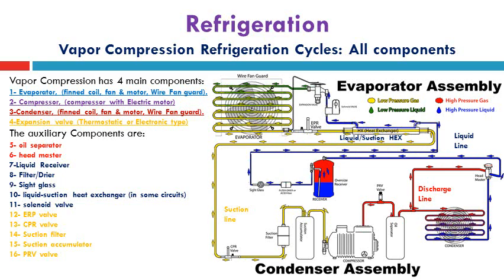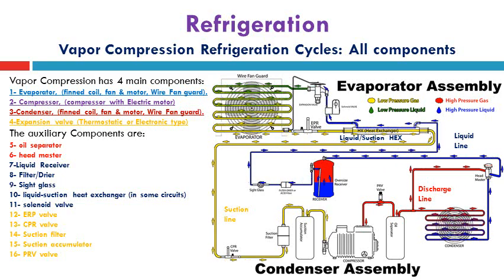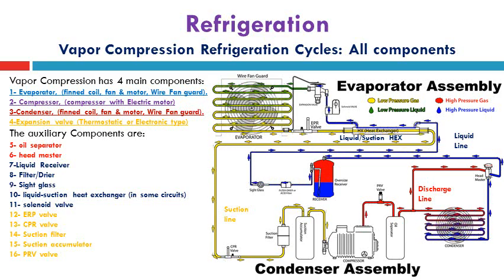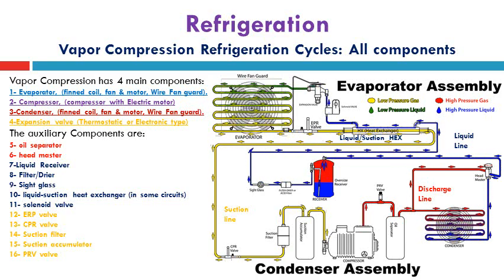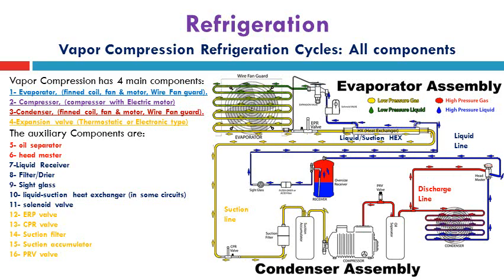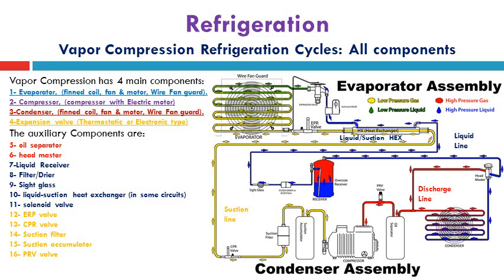This heat exchanger may be helpful to increase the COP with some refrigerants. A study must be performed on the effect on the COP of the superheating of the gas going out through the evaporator before entering the compressor, together with the subcooling which must happen to the liquid refrigerant going out from the condenser.